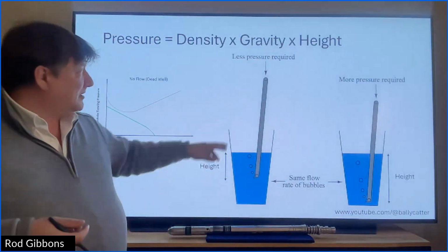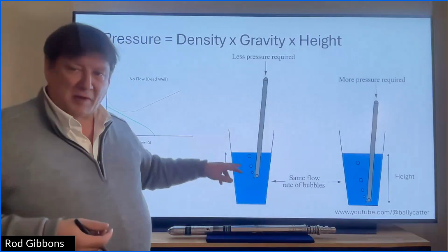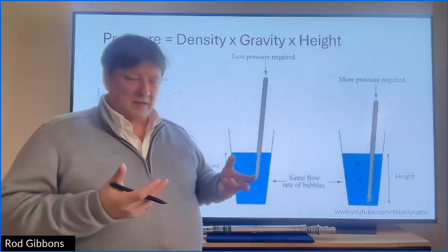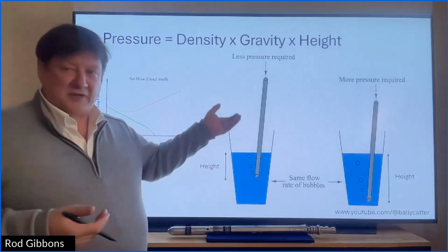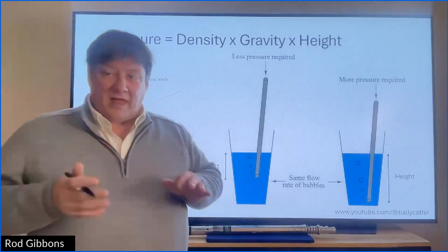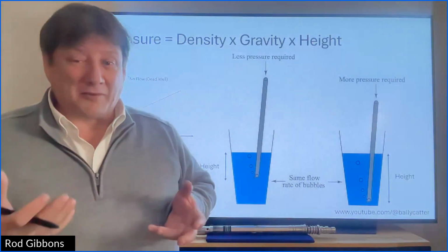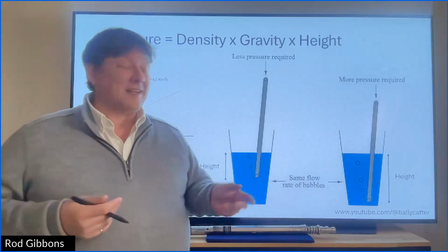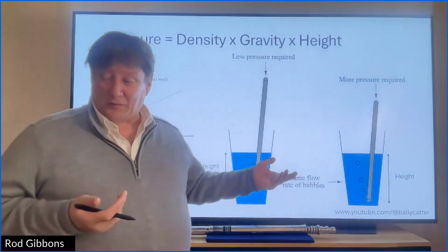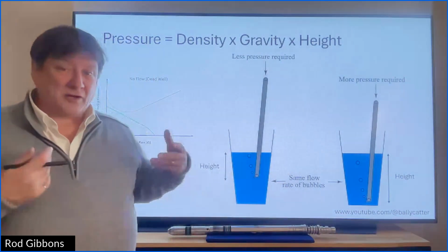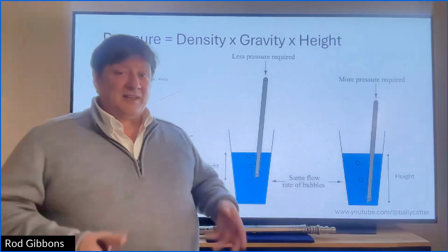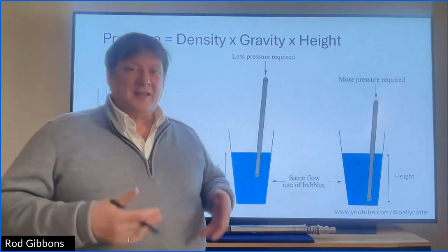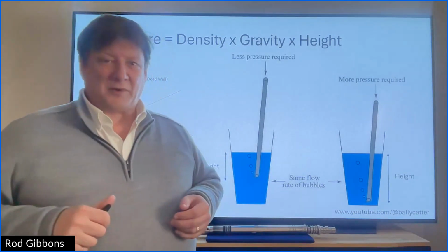Here, blowing bubbles into our column of water lightens the fluid column and puts it higher up. There's no better form of lift that exemplifies that than gas lift, because this is exactly what we're going to do. We're going to bubble gas into our fluid column, using the well architecture to lift reservoir fluids.